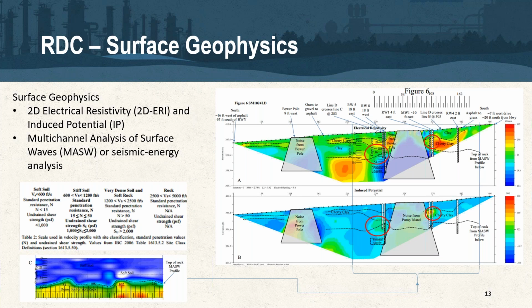And then the bottom left there, this is a seismic profile, multi-channel surface wave analysis of a site, same site. And you can see how combining these different geophysical tools will allow us to look at areas where we may want to target denser rock, or if we're doing a transition zone where we need to know that softer or weathered unit is that we need to drill into to actually treat this contaminant's concern in that interval.